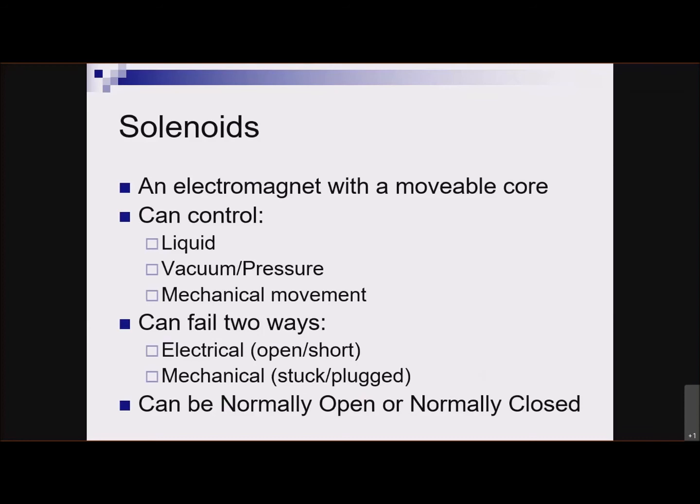Its normal position when it is not energized is to allow air to flow through it into the canister. And when the computer wants to seal the system off, it energizes that solenoid, which then closes it. Normally closed solenoid, as you might guess now, right? On the bench, in the box at the parts store, whatever, it's closed, nothing flows through it. And when it's energized, it opens and then things flow through it.